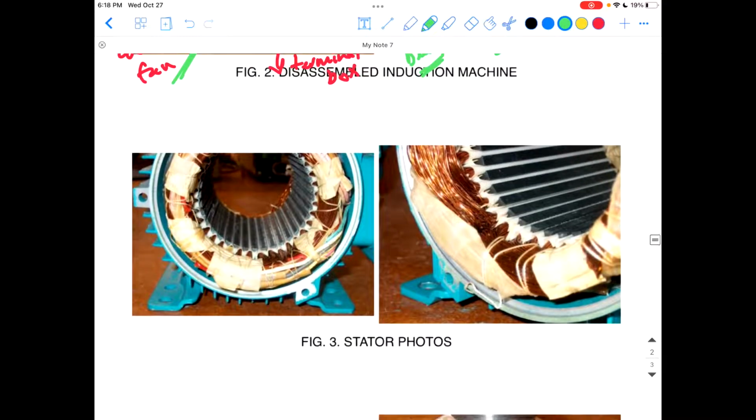Okay, the same thing here. So that is the stator, like you're seeing from inside. So you have these slots inside here. Those guys are the slots where you're placing your winding inside them, and now those are your winding. If you can't see them, they are just winding. Those are the three-phase winding of the stator.